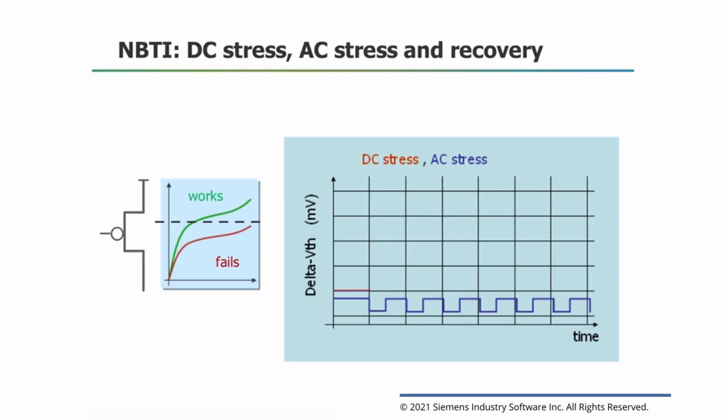Researchers have also investigated a rising number of second-order effects, such as the impact of bulk biasing and the chosen layout geometries, like for instance in multi-finger structures heavily used for analog and RF applications. However, a widely accepted consensus for unified modeling is lacking, and many effects are still modeled with semi-empirical equations that fit experimental data. To conclude, the degradation profile should model both static and dynamic types of stress.